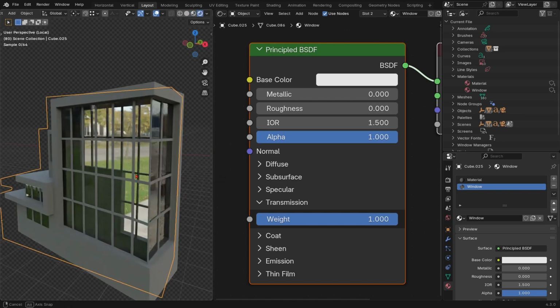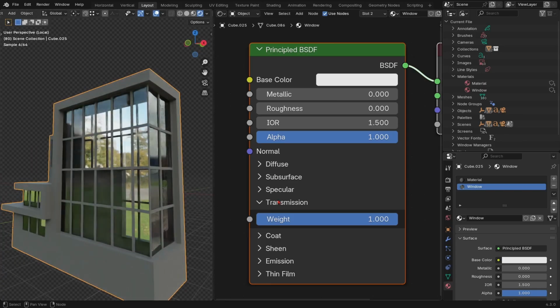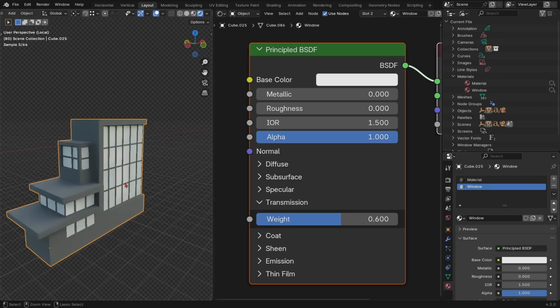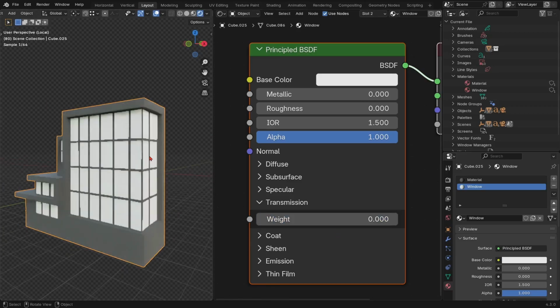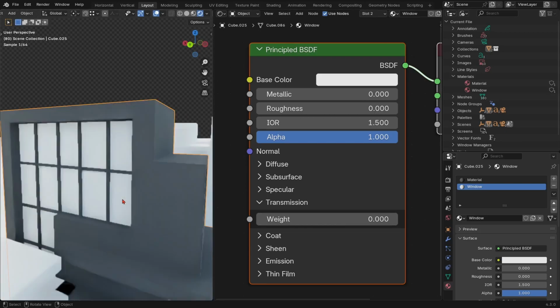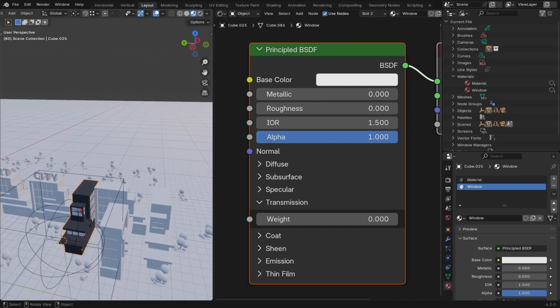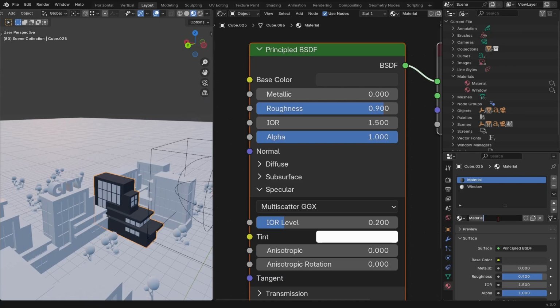Switch to render mode, we will see it like so. Of course, we can use it later in the upcoming projects. So let's turn it off for now. And now let's press numpad slash once again, and we go to material preview, which is a bit faster. And let's rename this material to black or dark gray.